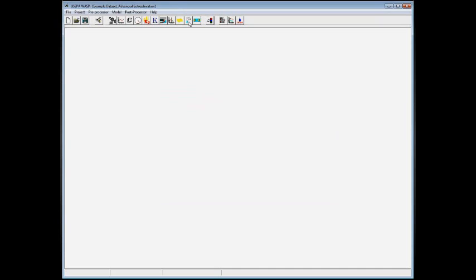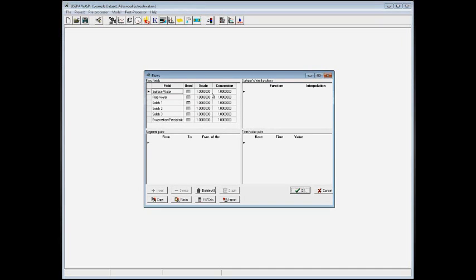The next one is flows, and we are going to enter flows here. Now, when you're using WASP to do the hydrodynamics, you pretty much have to tell the model where the water is coming from and where it's going to. So there are 6 flow fields in WASP: surface water flow, water flow, 3 solids settling and resuspension fields, and then evaporation and precipitation. We're just going to use the surface water flow field, so I'm going to click used here,